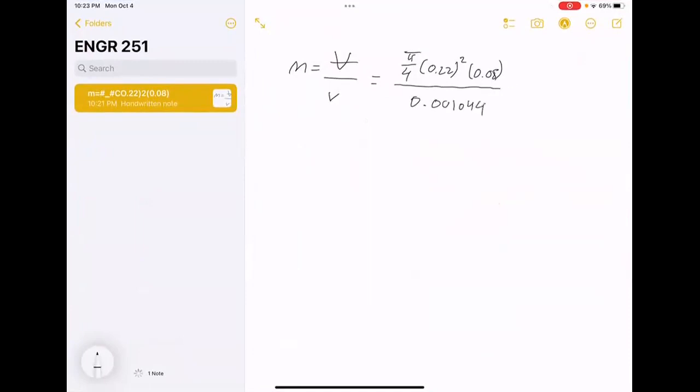0.04. And if we calculate all this, we're going to get the mass of water that left in those 40 minutes. And we can see by calculating this that it would be 2.91 kilograms. So we've lost in 40 minutes 2.91 kilograms as vapor. That means in 40 minutes we've given enough energy to vaporize 2.91 kilograms of water. But how much energy is that?